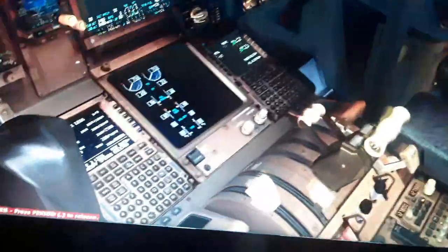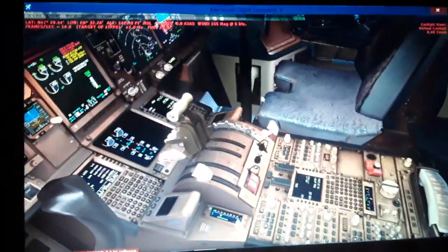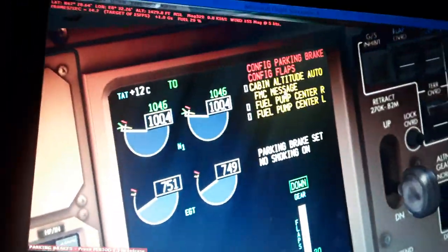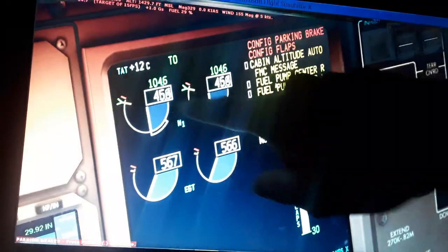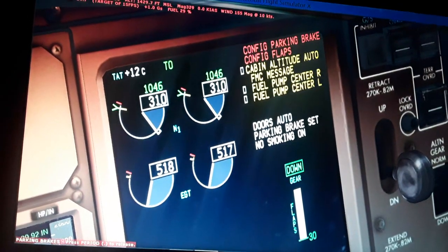We have also a couple more switches, the takeoff ground here and the auto throttle disconnect. This switch disconnects the auto throttle here from the thrust system. So we use only manual after we disconnect the auto throttle in flight. So we can move the thrust levers forward. You will see the engine's rating here, as I told you before. The N1, the left and right engine, the low speed starter, the takeoff limit green. As you see, it takes a couple of seconds for the engines to pull up or pull down.